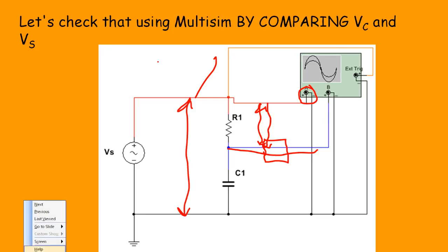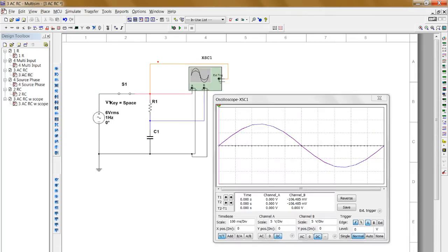We're going to go into one final simulation. So here we are at our simulation, and we're going to simulate the voltage across the capacitor. You can see we've got the oscilloscope channel B hooked up to measure the difference in capacitor voltage, just like we had before, where this is the ground and this is the capacitor voltage. So channel B, which is blue, is going to be the capacitor voltage. But now we've got the situation a little bit different. Now channel A is hooked to the output of my function generator directly, and that's how we had it before.